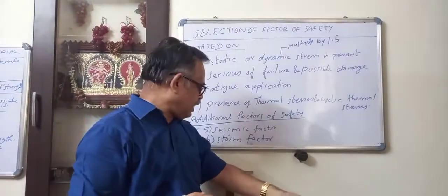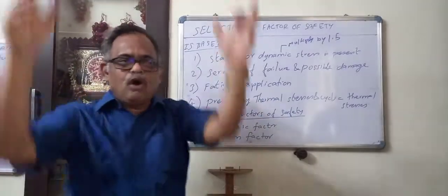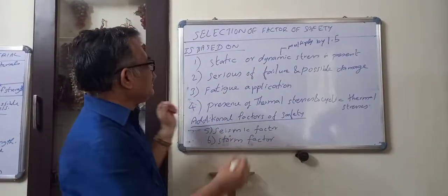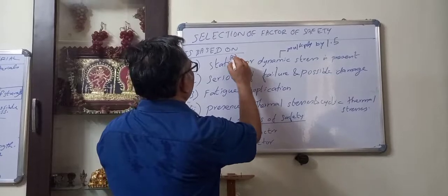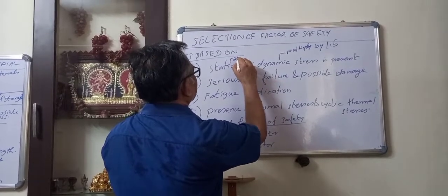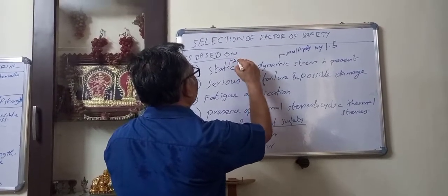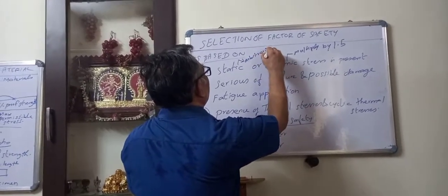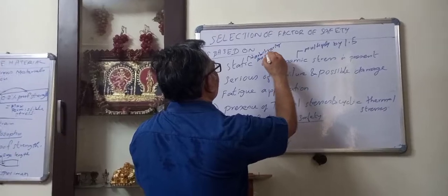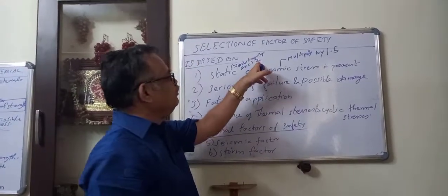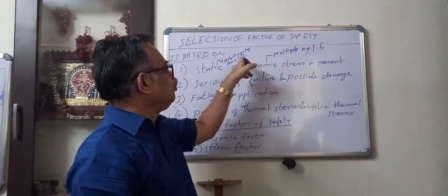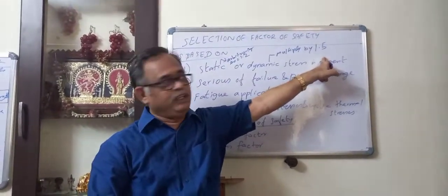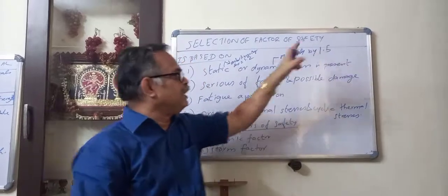So if a crusher is running, for the same load of the crusher, everything, you can define. If your static factor of safety you can select based on experience, or arbitrarily, for example, equal to 1.2, then if it is going to be dynamic stress, 1.2 multiplied by 1.5. That should be the factor of safety. That is one condition.